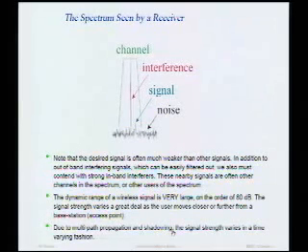There's also shadowing, the fact that I could be behind a tree or behind a car when I'm communicating and all of a sudden my signal strength drops a lot, or I might be around a corner, and so forth. And this is all happening in a time-varying fashion, so my receiver needs to detect the signal strength and adapt to it.